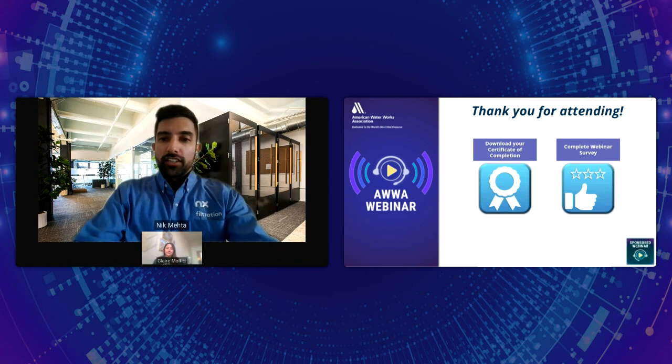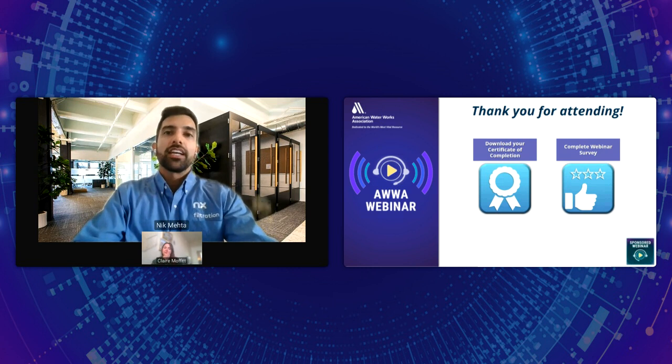And then the last question here I'll quickly jump to is, you mentioned, hi Nick, you mentioned a 5 log credit. Does this mean you can guarantee an LRV of 5 through pressure decay test? Yes, the answer is yes. These membranes can be pressure decay tested inline in the membrane skid that we have, and we have P&IDs for that. It's something that the membrane is certainly capable of.